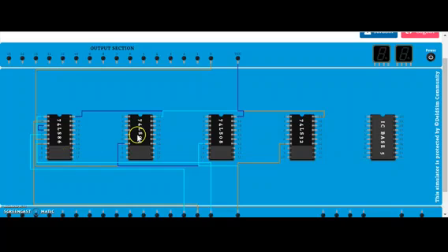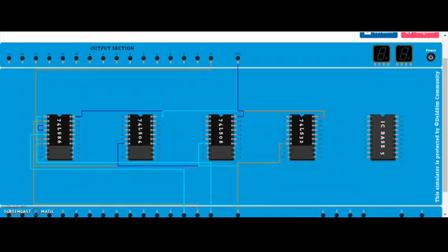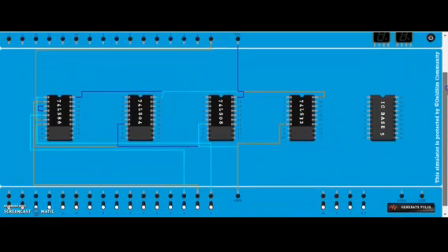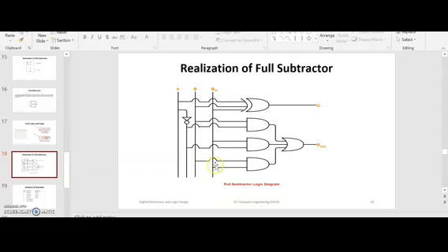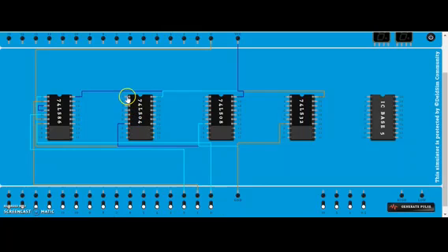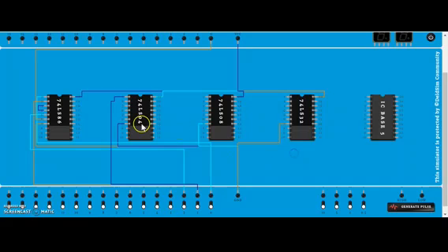Now we will move to the B out. So for B out we'll need the first AND gate. See this, this is having B and B in, so we will AND it together. So this is B, and the second input to the AND gate is this, this is B, and this is B in.